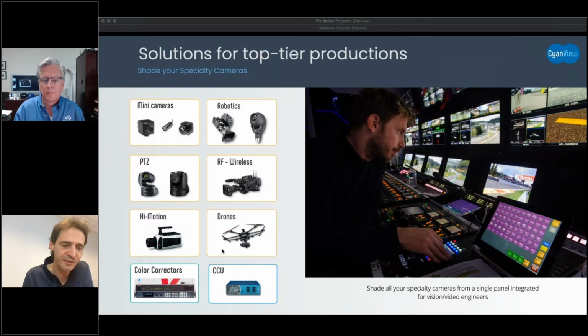And the reason we developed that is to be able to match cameras. Most of the standard color correctors have a proc amp, so a video processor inside, which is a legalizer, and you can normalize the signals. You can adjust the blacks, the gamma, the white to make the signal clean, and the white would be white. But if the red is pink, you cannot take the red and put it in the right place. It's impossible. If you take 2 different cameras with 2 different sensors, it's impossible to match them. That's the reason why we said we need to develop something that will act more like a CCU, that will allow you to have the controls you need to match cameras together. And I will just show this right after.